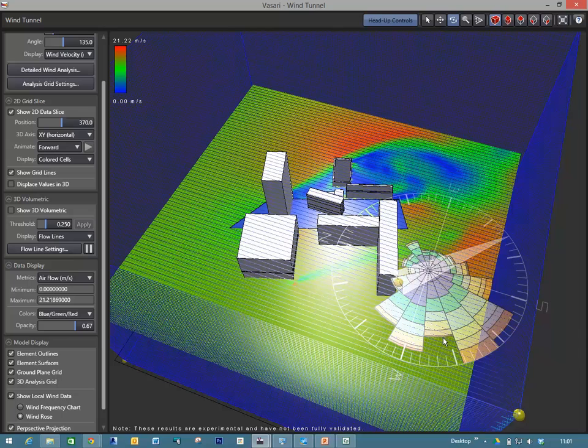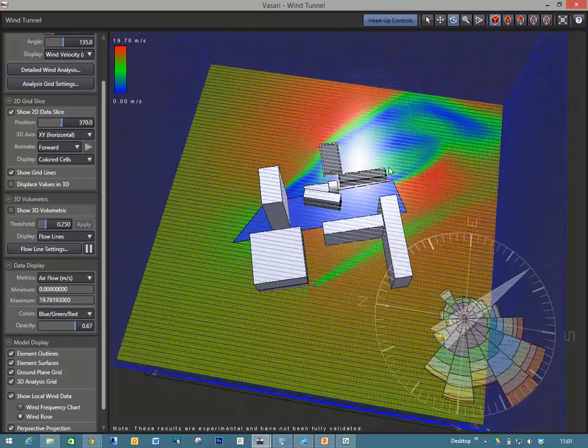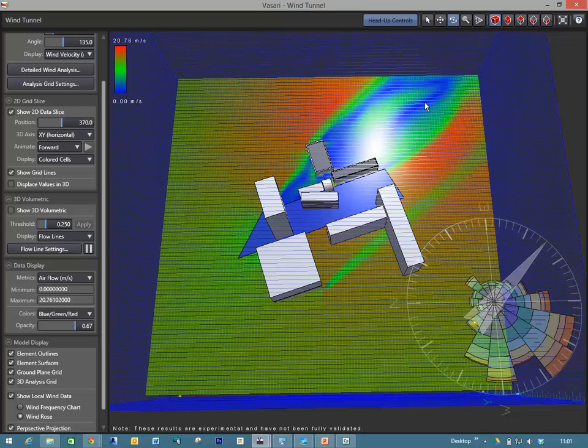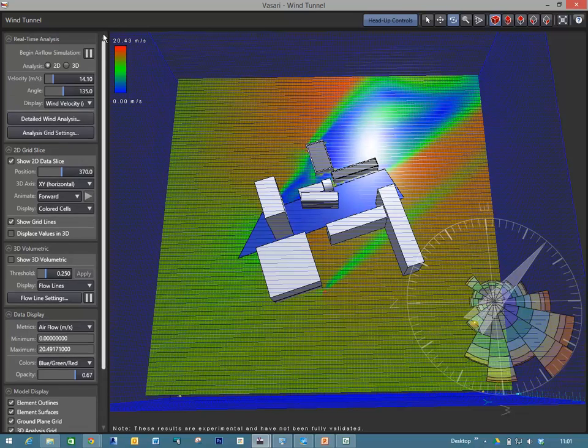So in terms of how you would simulate the wind on that site, obviously for any given site, the wind is going to move, and it will be different throughout the year. So you can't simulate just for one snapshot in time. What you need to do is sample. And the normal methodology would be to take some samples at the highest velocities on that site.